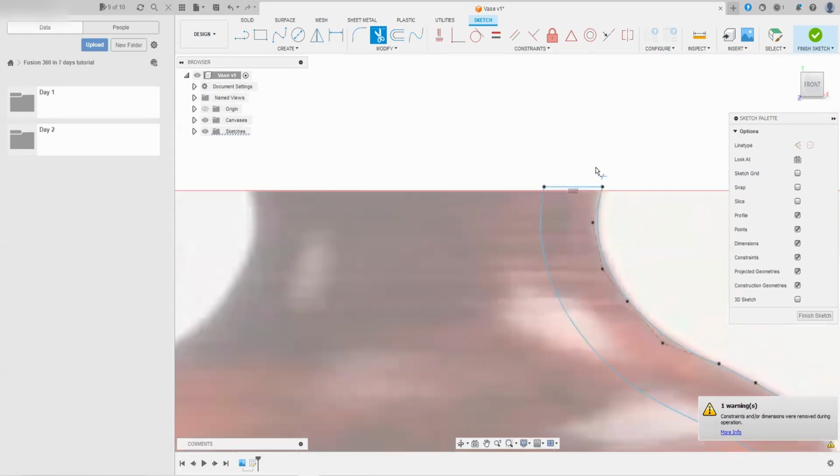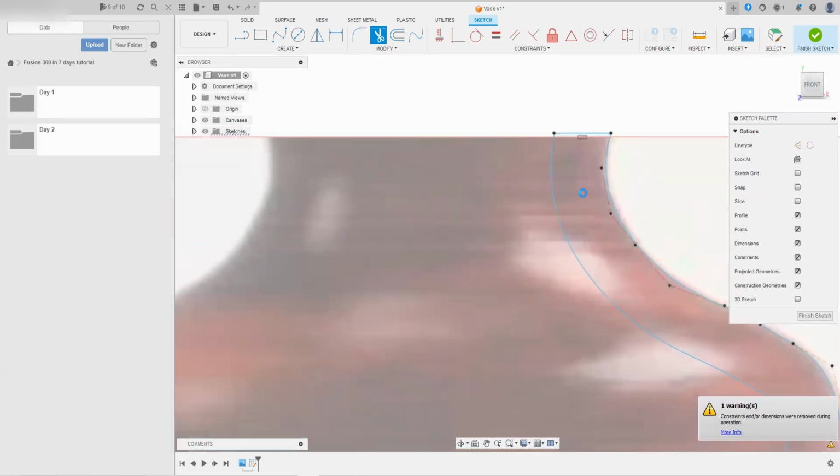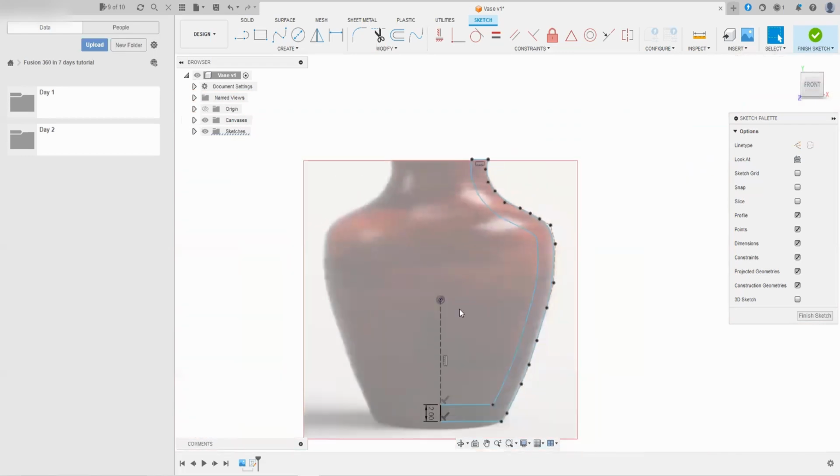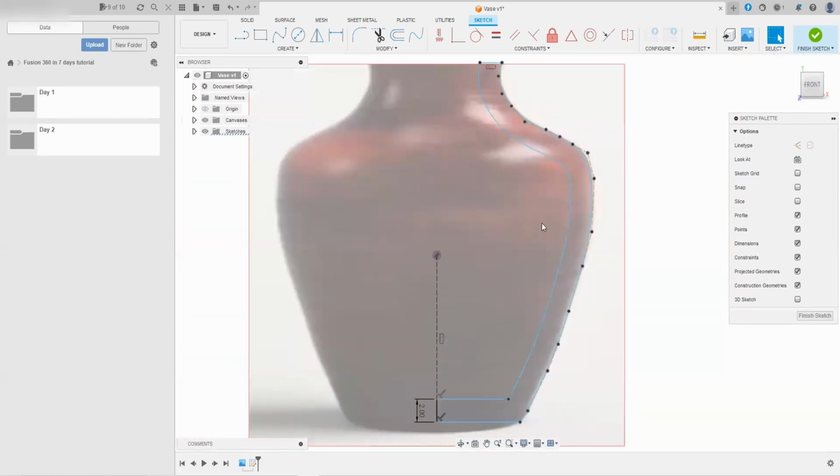And there you have it, a closed sketch that has been created representing the cross-section of our vase. As mentioned, you can tell that the sketch is enclosed by the blue shade that has been added between the lines. If the sketch was not closed off, this blue color shade would not have appeared, which will lead to problems when trying to convert it to a 3D geometry. Actually, the program will just not let you do that, so keep that in mind.